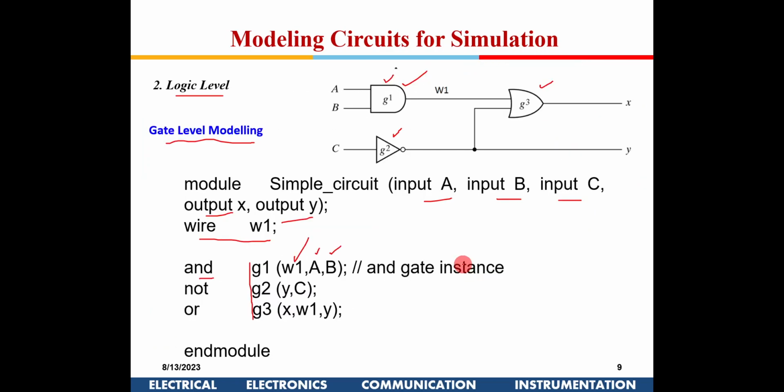And gate level simulation is useful because, if you remember from the first class, when we are incorporating DFT, design for testing, then you want to observe the output values in between also, and so gate level modeling would be helpful in that particular case.